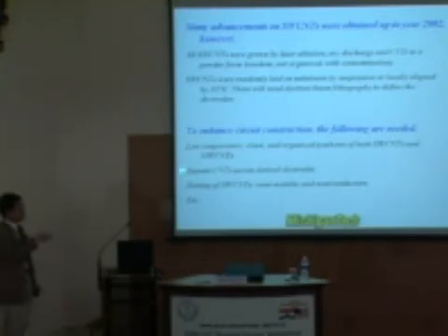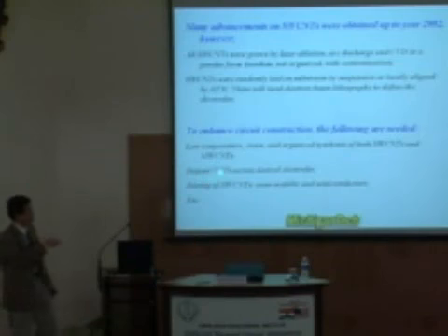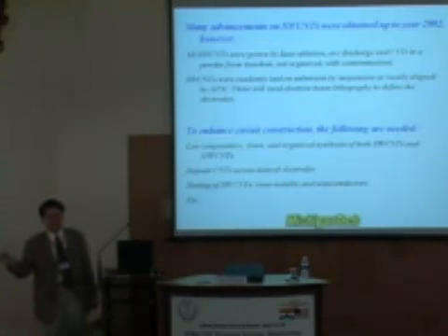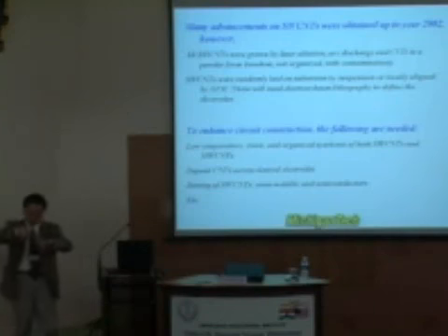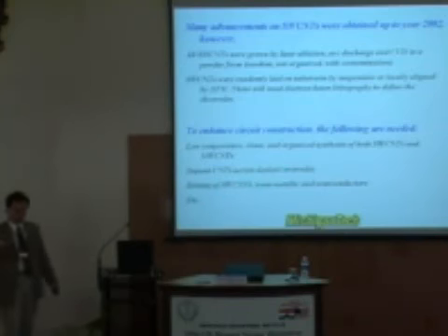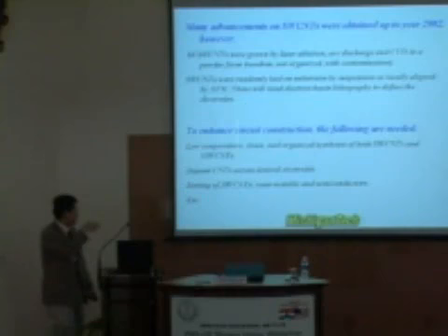And you will need to be able to deposit carbon nanotubes across a pair of desired electrodes. For instance, within the chips, you might have 1 million pieces of the electrode. You want each pair of the electrodes to have only 1 nanotube aligned across them. And also, you have to be able to sort single wall carbon nanotubes into semiconducting tubes or metallic tubes, so that you can choose only the semiconducting tubes for your applications. And so on. The list will be very long.